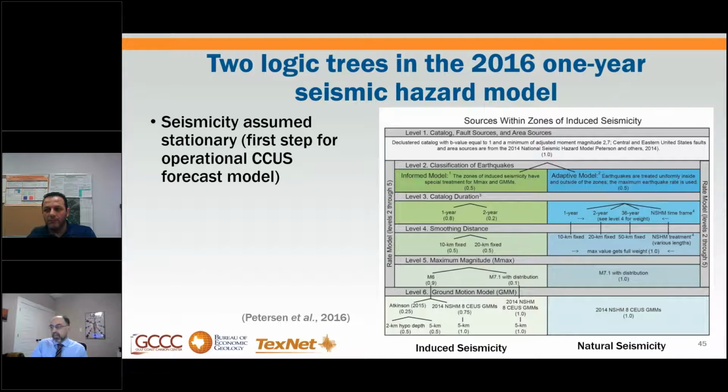Now, the last thing is the ground motion model. That is a huge thing here. You have to use different ground motion models because the general and national seismic hazard models cannot apply very easily in that case. What I suggest for that is to use your own ground motion model based on your observed data. If you have observed earthquake data, use your own ground motion model based on that.